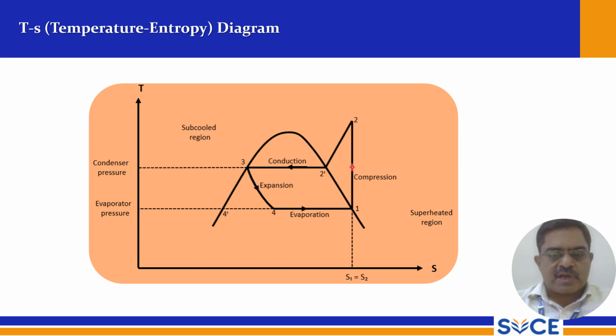And here during this ideal cycle, if you see, this is ideal cycle 1 to 2, the entropy is constant, S1 equal to S2, but actually it is not happening in actual cycles. In practical situations, it goes in this line. So this is the line, and this is not actually an isentropic process, there is a change in entropy. So actually S1 is not equal to S2, but in ideal cycle S1 equal to S2. So this is the difference between ideal and the actual cycles.